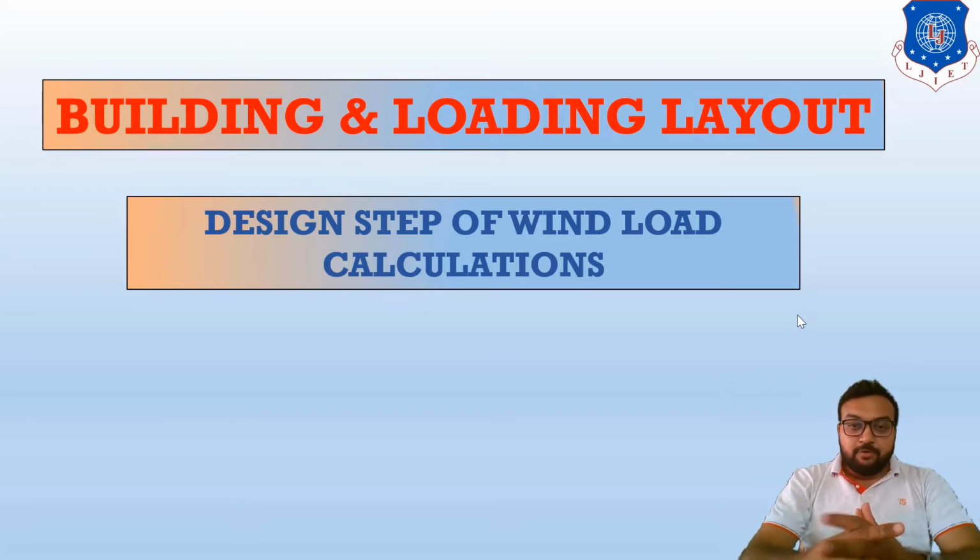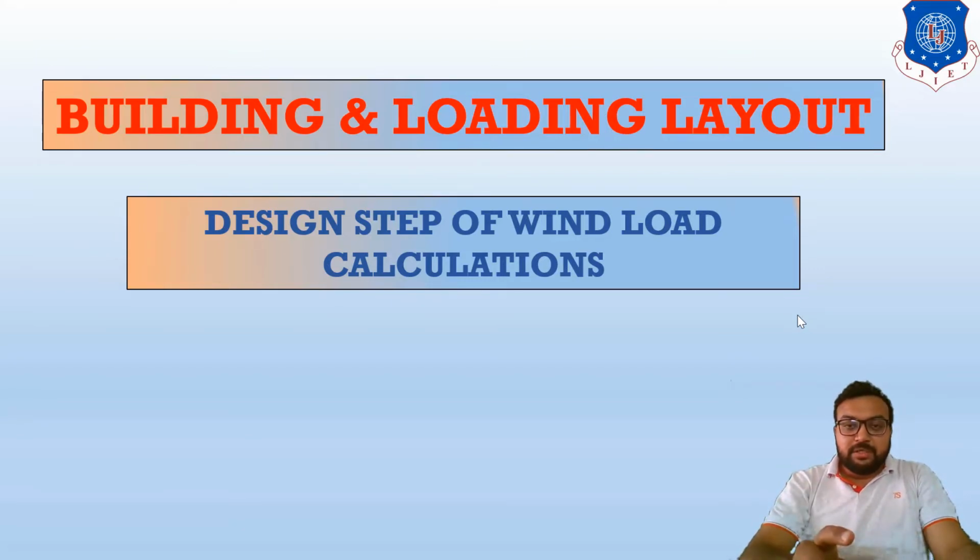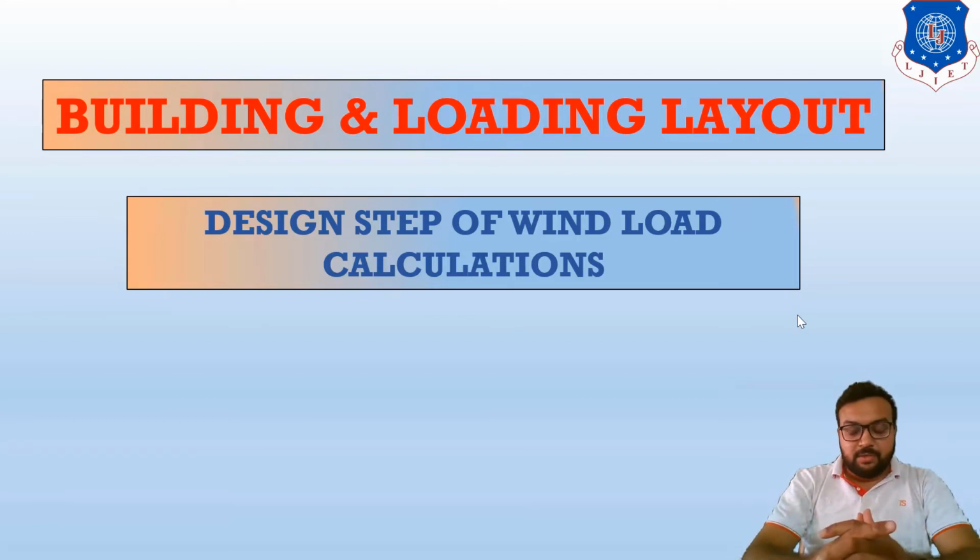Second one is live load, and you all know that live load is also called imposed load. The calculation of imposed load is as per IS 875 part 2. Third one is wind load calculation. Wind load calculation is as per our new IS code provision, which was published in 2015.